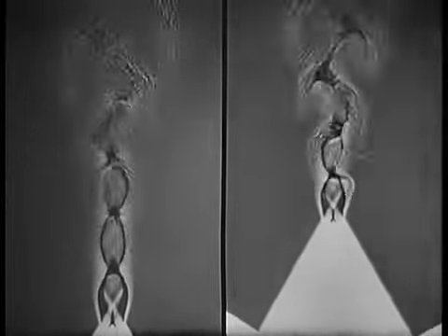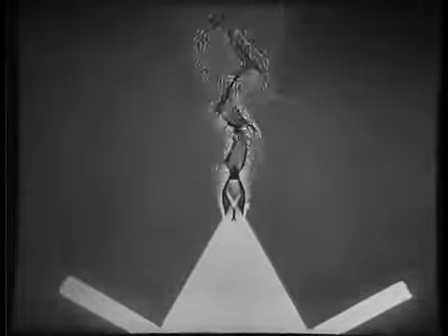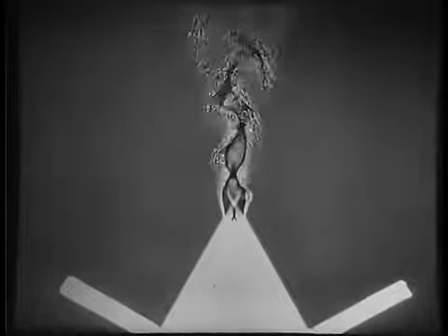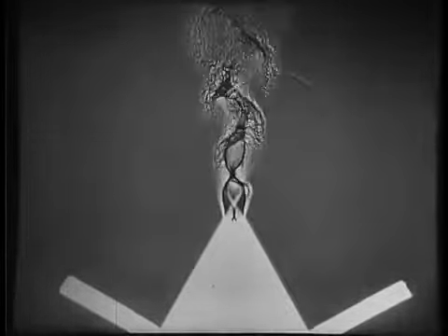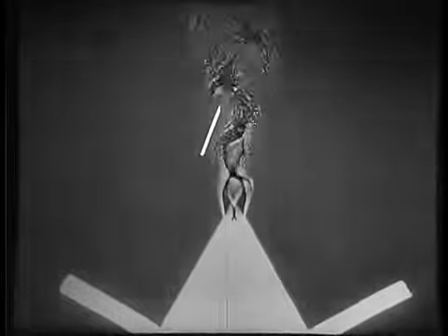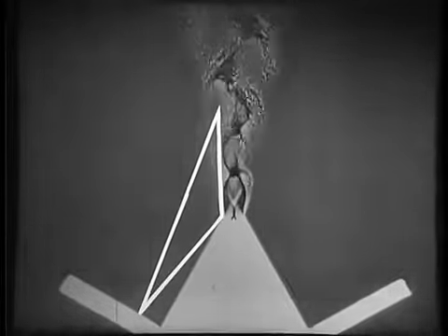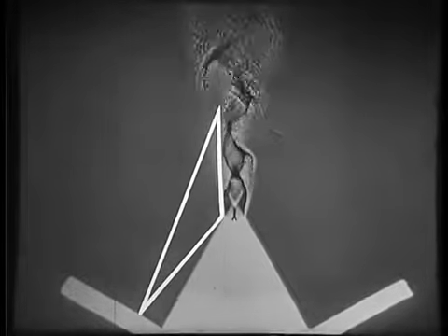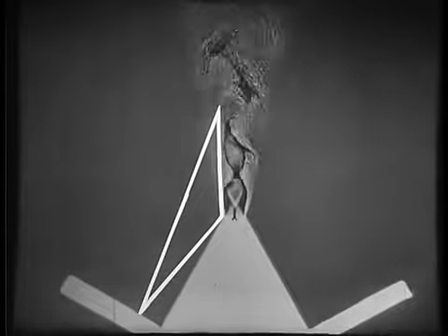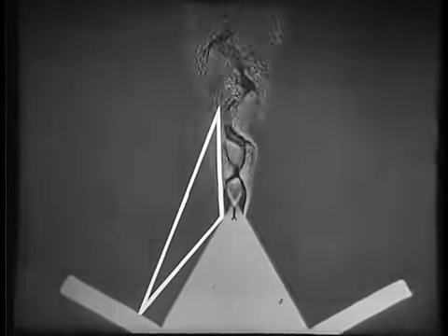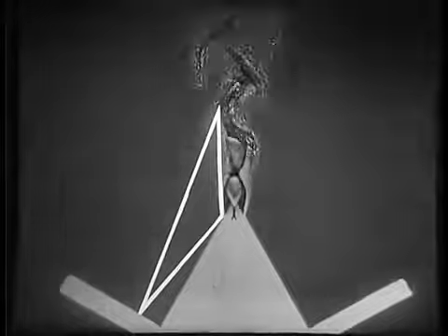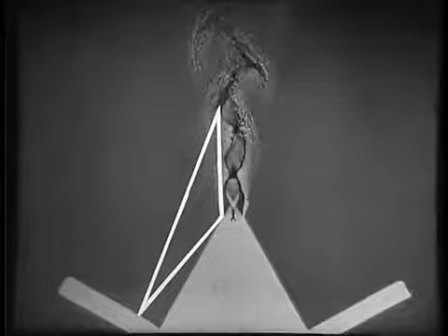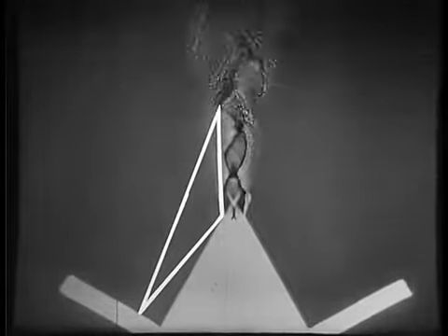The following model gives an explanation of what we have seen. Suppose somewhere in the jet a sound pulse is generated which expands cylindrically. Part of this sound pulse is reflected by the reflectors. When this part of the pulse passes the nozzle edge, a vortex develops, or in case of an existing vortex, it is enlarged. The vortex is swept along the cell boundary and its size increases. This process may be regarded as mechanical amplification.